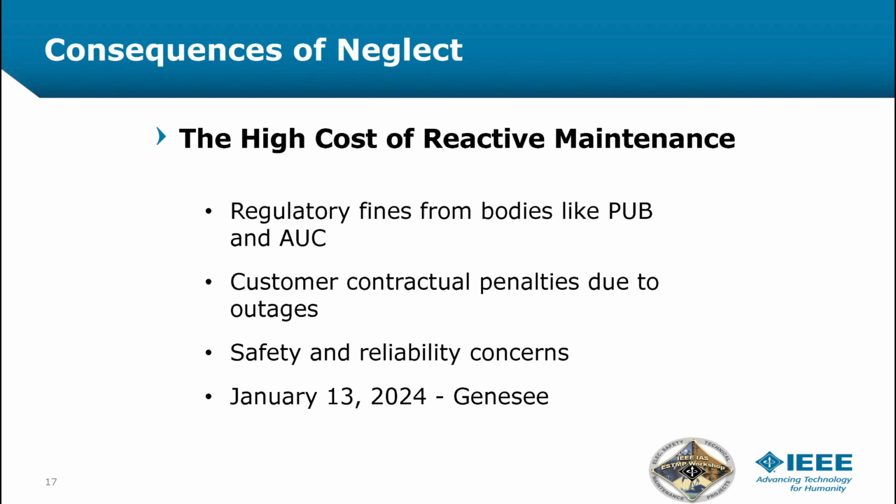Two other generating facilities were off at the time during that cold snap, causing all cell phones in the province to come on as an emergency alert, asking them to shut off load. It was peaking a little over 11,000 megawatts, and 200 megawatts was dumped within 2 minutes, helping to keep the system on and avoiding a brownout.